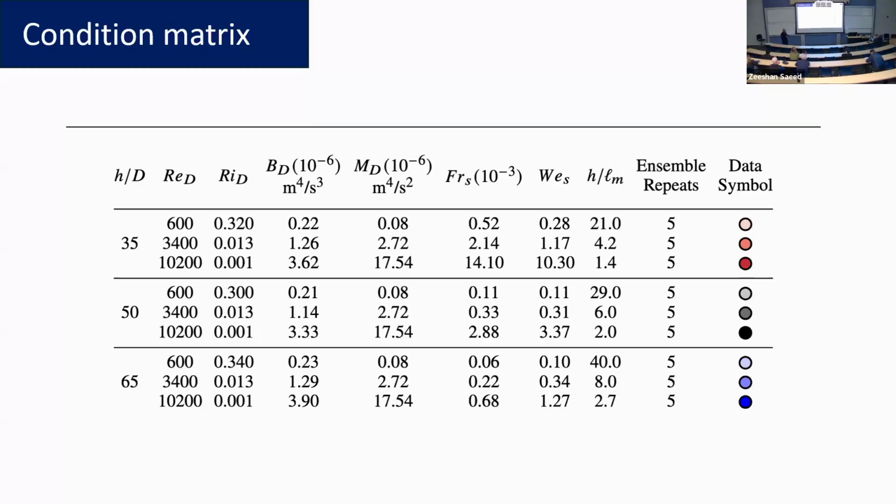So it was not a vigorously perturbed free surface in the sense that the perturbations were very strong, but they were mostly dominated by gravity and they were stabilized by gravity. That is reflected by the small Froude number. And then the Weber number is customary over here because everything is controlled by gravity and not the surface tension. And then conditions ranging from, as I said, pure jet to pure plume-like conditions.